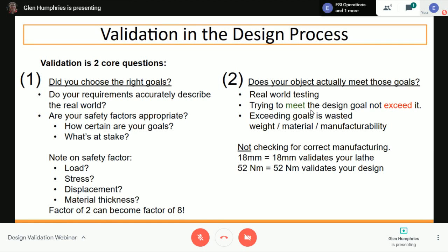So where they thought they had an appropriate, not too big, not too small safety factor of 2, they actually had drive shafts that you could probably put in a truck. And they were carrying these things around the racetrack the whole time. They were too heavy. They probably cost more money, and they could have been smaller. So yeah, look at where your safety factors come in and affect the actual mathematics of your component.